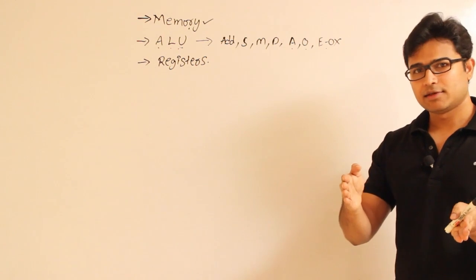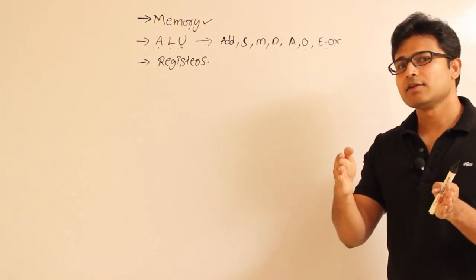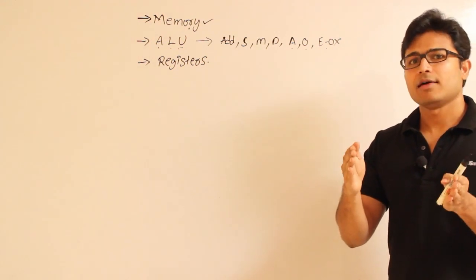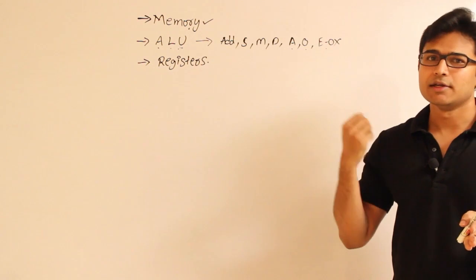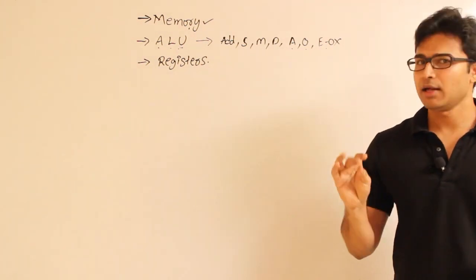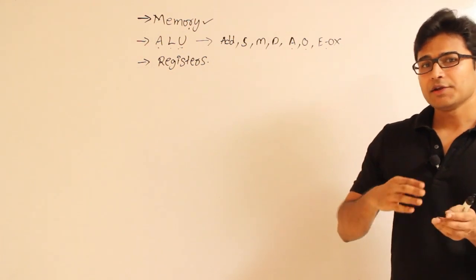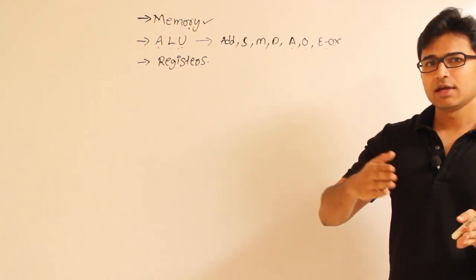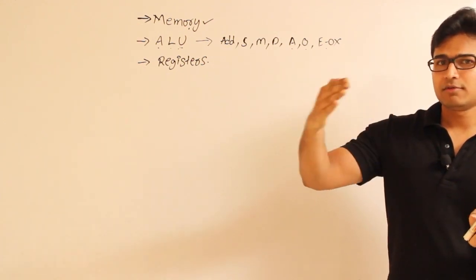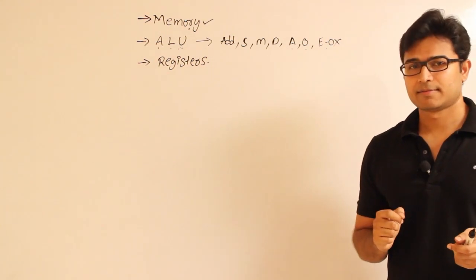One thing is, if you are going to put 8 flip-flops together, we can use it as if it is an 8-bit register. Fine. And along with that, we can parallelly load them or parallelly read them. So we can do parallel input, parallel output. I have shown you in digital. And similarly, we can shift them, shift right or shift left. It is nothing but shifting the bits from one flip-flop to the next flip-flop. We have already seen this, right?